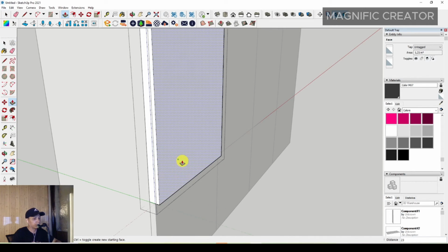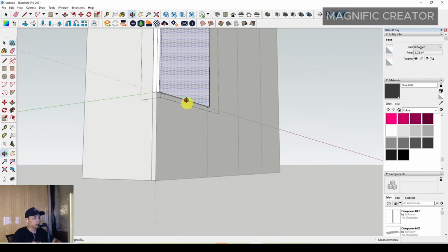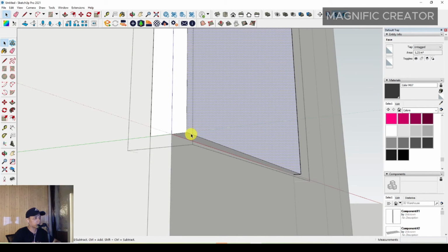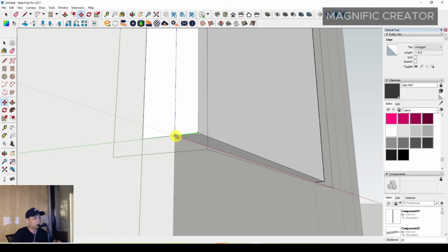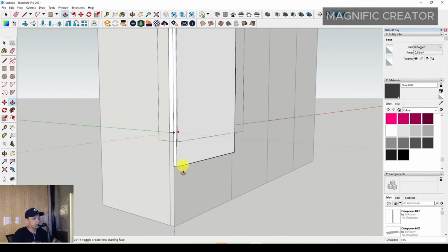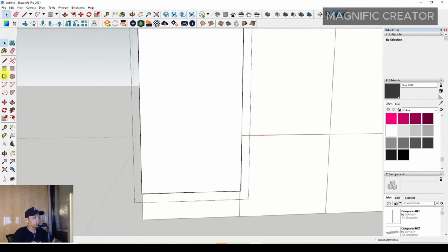You can make maybe 20 more thickness. Then you can select this line and then just select move and press control to duplicate it and position it on this position, and then you have to push it down. Okay, you have to push it down, maybe it's around 350 millimeter, and then you can use the 2-point arc to make a uniqueness of this upper door of the wardrobe. Anyway, then you can set the value of this segment with 100 and just press enter.